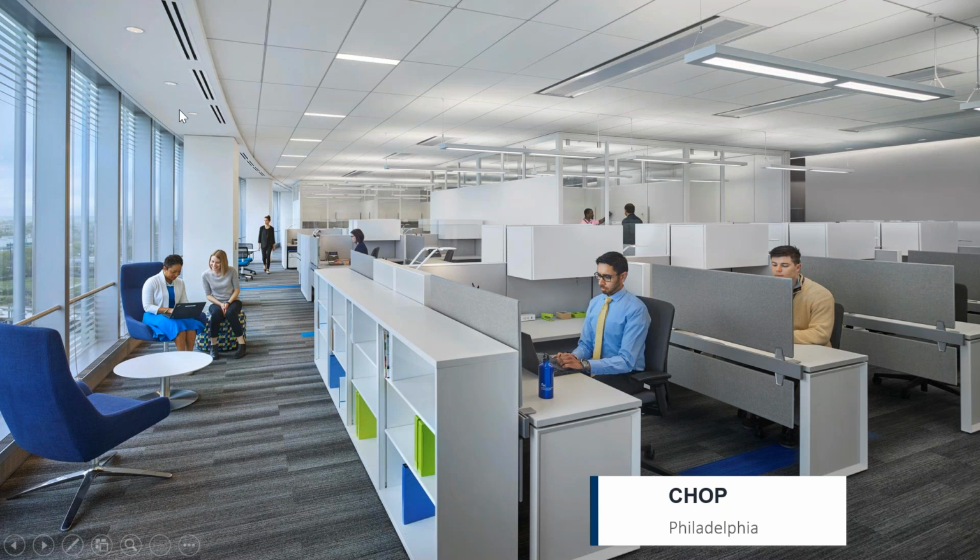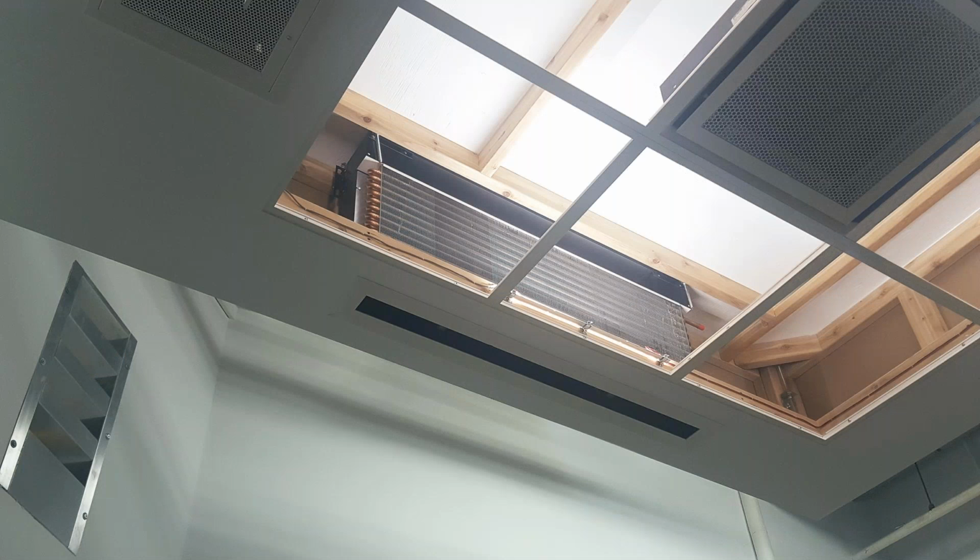the vertical discharge. What's happening here is there's a little bit of a reveal or a gap between the mullions and where that hard lid ceiling starts. And so the warm return air from the glass, from that perimeter, is being pulled up through the ceiling and cooled and conditioned through that ACBR unit that's concealed above the ceiling, and then supplied into the space. So that has a 4-pipe arrangement along the perimeter to accommodate heating and cooling.